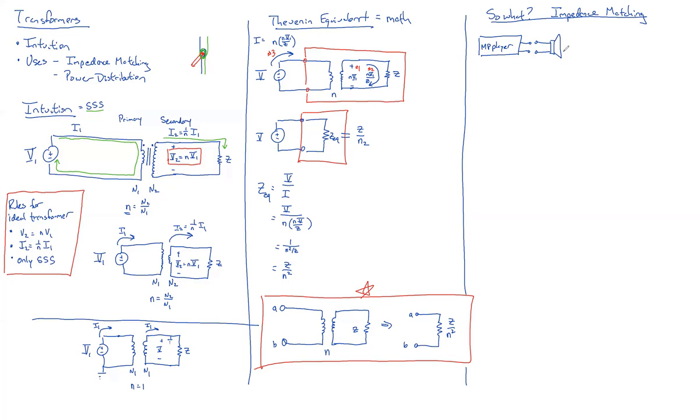So you already know why, right? Why doesn't it work? The MP3 player puts out about ±1 volt. The speaker works great on ±1 volt. You put them together, you get nothing. What's going on? Well, does that MP3 player have a Thevenin resistance? Right, an implied Thevenin resistance, so it's not actually putting out that.